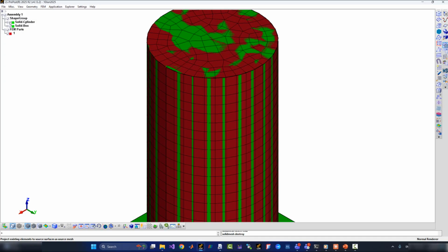And you may notice we have active the solid cylinder and solid box that we defined. The solid cylinder is no longer necessary, and when we eventually save, we will simply save a keyword file for LS-PrePost, which only retains the mesh information, the parts and nodal coordinates and element connectivity, meaning these geometric entities will be lost anyway.